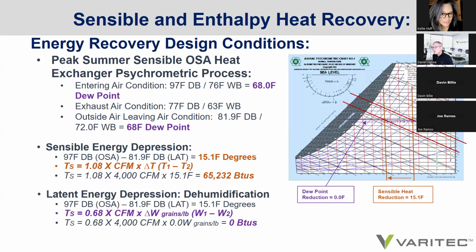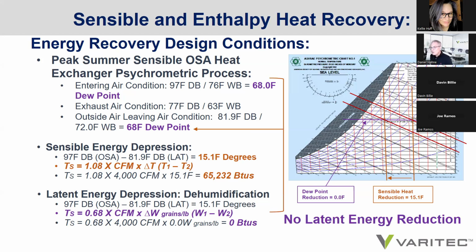However, if you look at the latent energy depression, there is zero in a sensible heat recovery solution, which may make sense if you live in a very dry climate. Could make all the sense in the world, and there are various other considerations as well. But again, you can see psychrometrically that the latent component is unchanged during sensible heat transfer.